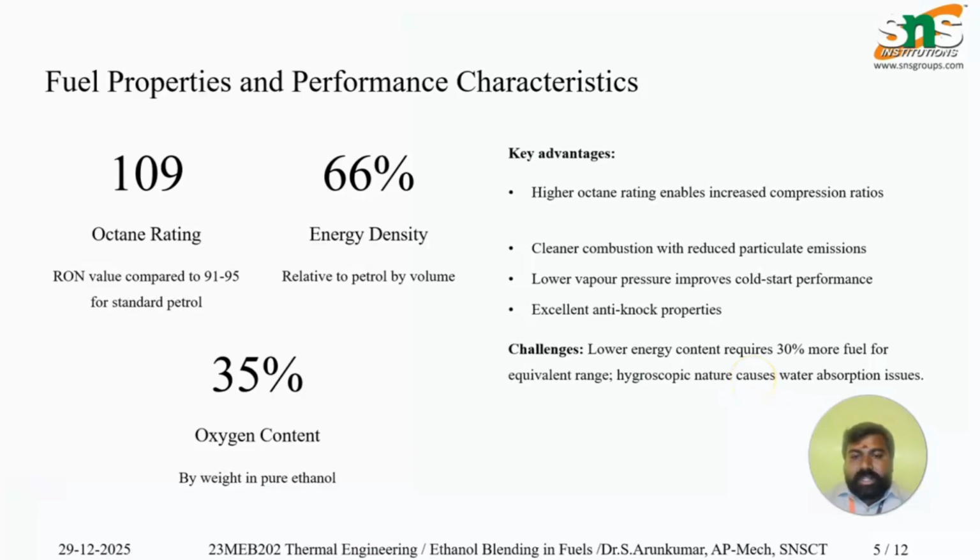Some of the key advantages are a higher octane rating that enables increased compression ratios, cleaner combustion with reduced particulate emissions, lower vapor pressure that improves cold start performance, and excellent anti-knock properties. Some of the key challenges are lower energy content, which requires 30% more fuel for the equivalent range, and hygroscopic nature, which causes water absorption issues.